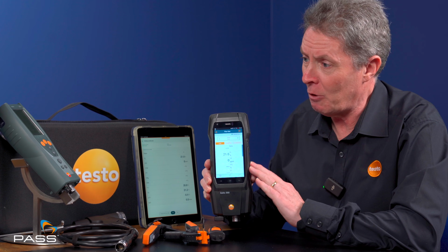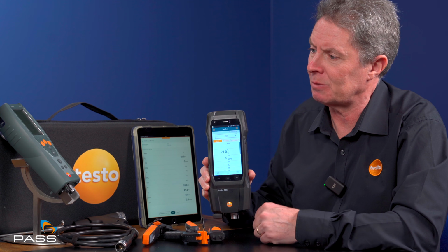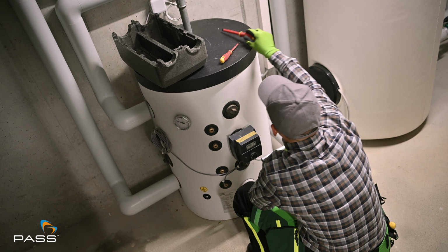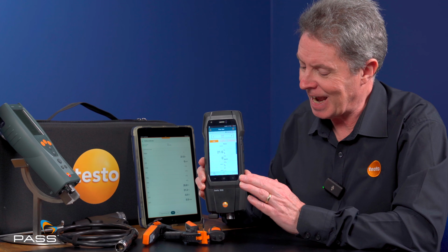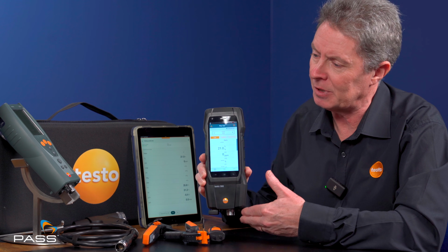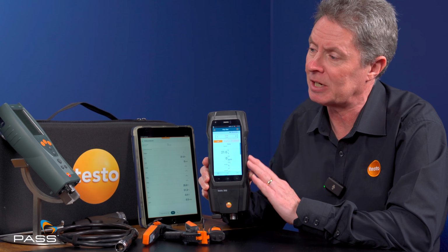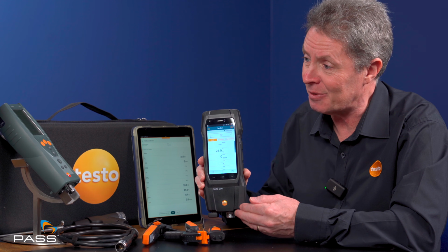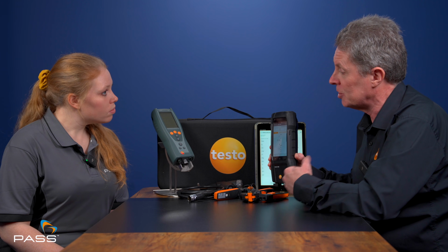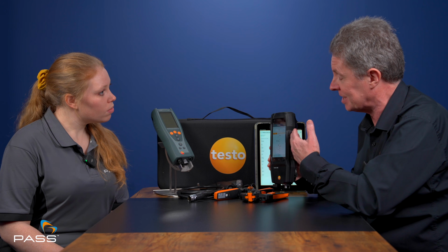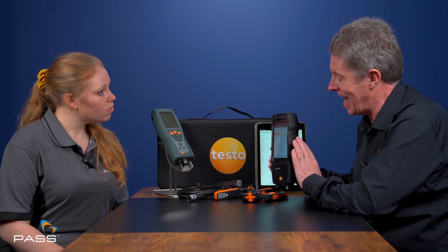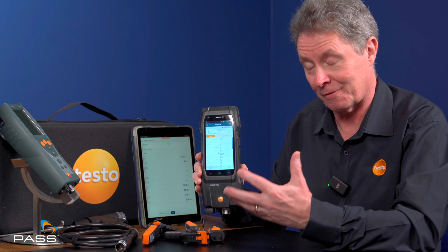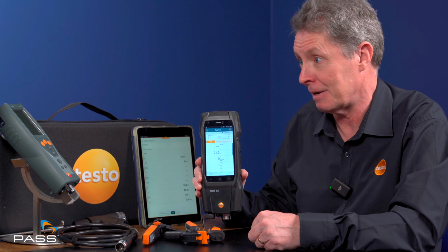With the LL unit, what we have is an auto dilution system. So on large commercial boilers and burners where a high CO spike can be problematic, the idea is it actually has a dilution system. So what happens is when it notices it's getting towards the maximum range of the sensor, a metered amount of fresh air is added into the measurement flow, if you like, so it dilutes the readings that the sensor is seeing. That actually enables the LL version to read right up to 30,000 parts per million of CO, which is a very, very high capability for any flue gas analyzer.